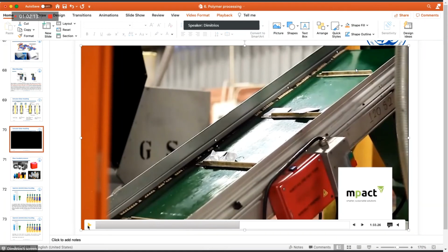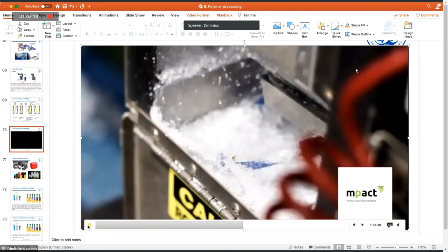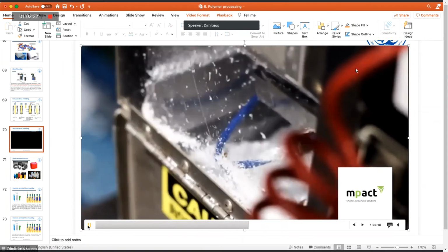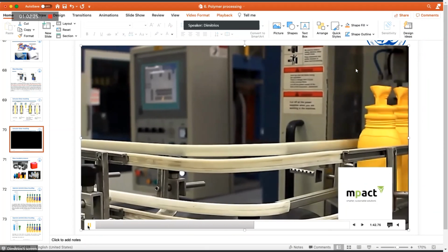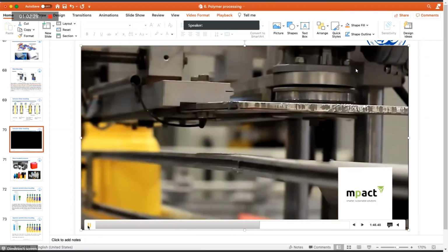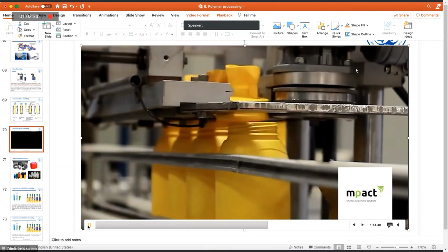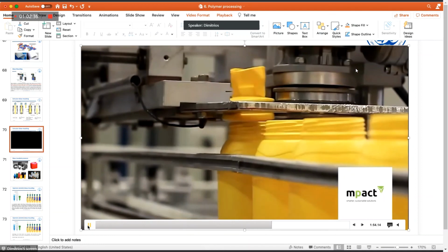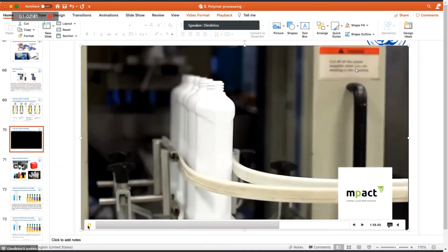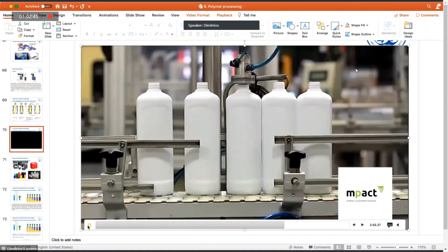And I want to show you one final part of this video, which is very important. This is quality testing. Here at this part in the industrial line, there is gas that is blown onto the bottle. And once the gas is blown onto the bottle, this machine essentially measures the pressure of the gas. If the pressure of the gas is lower than the pressure it puts onto the bottle, that means that there is a leak in the bottle, and that leads to a failure.